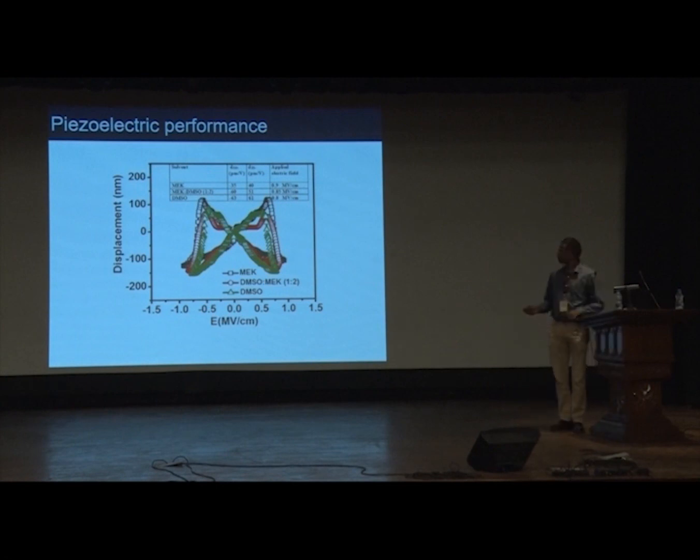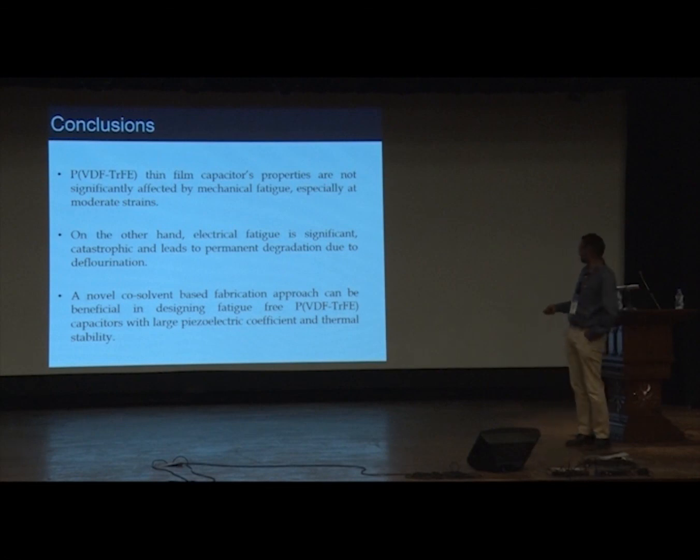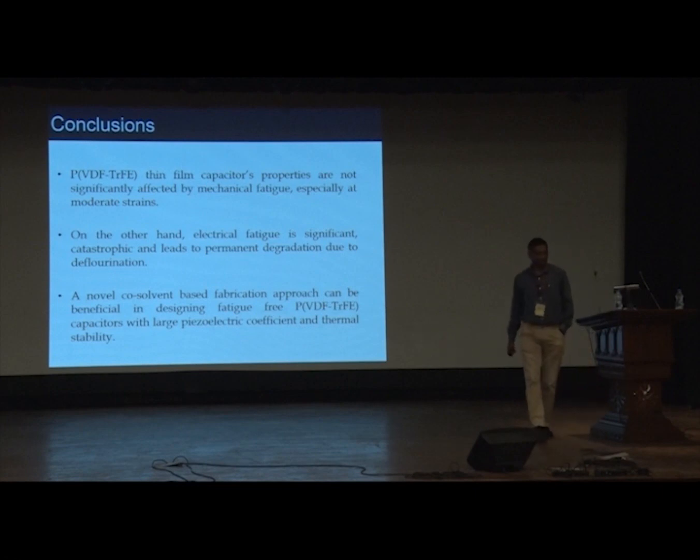So overall, to conclude, I would say we found that PVDF-TrFE thin films for flexible memory applications are not affected by mechanical fatigue, especially at moderate strains, which is the good news. What we found was that electrical fatigue is a permanent effect and it is catastrophic, but it needs to be improved upon. So we developed a method which is based on understanding the dipole moment of the solvent, how it affects the chain formation and crystallinity. We found that you can make fatigue-free capacitors with a large piezoelectric coefficient and very good thermal stability.